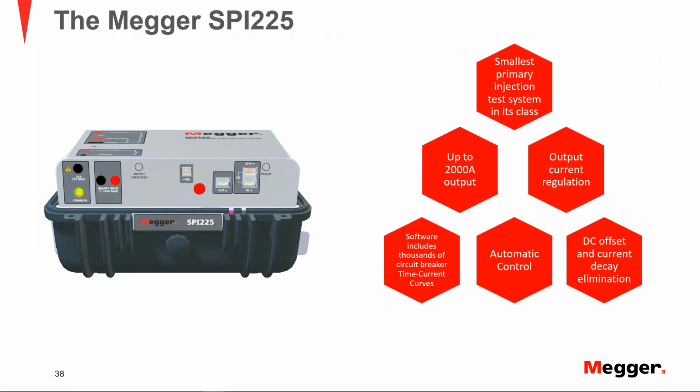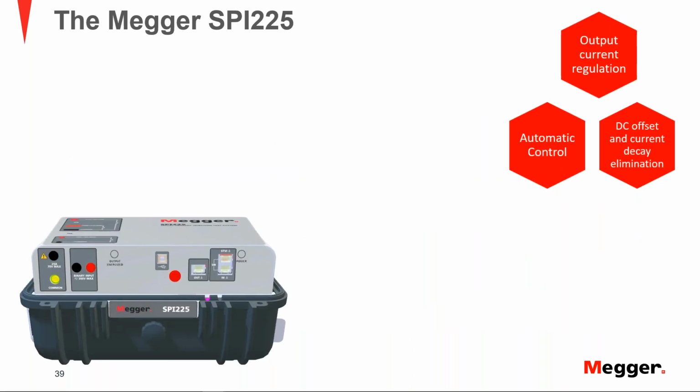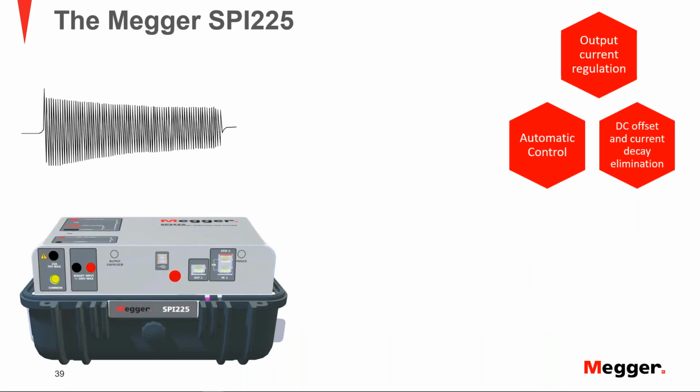Why am I saying that this is the next generation of primary injection testers? Well, we know the high current capability, and we can even get up to 2000 amps. It is the smallest primary injection system in its class, and the output current regulation control is really important. So let's look at that in a little bit more detail, starting with automatic regulation and the current decay elimination.